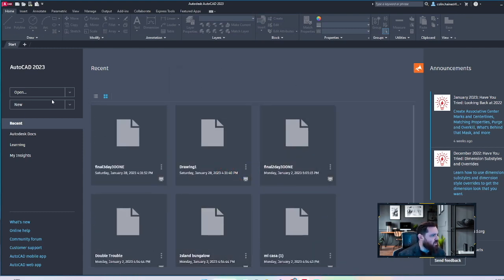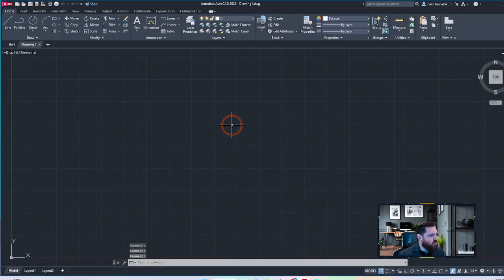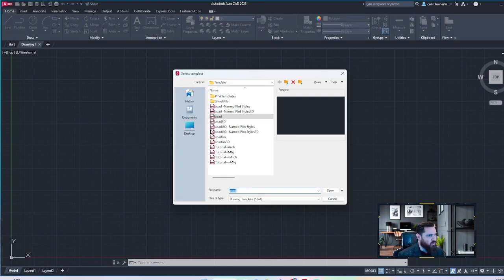But what you want to do from here is click on New, and that'll open a new document. If it's the first time you're ever opening a document, like I'll open another new one here, it will show you a list of templates. The one it defaults to, AutoCAD, gives you the general basic layout, the de facto default. There are use cases for some of the other ones. For example, architecture or manufacturing will give you a default title block if you don't feel like creating one yourself. But AutoCAD is just fine for our purposes of learning here.